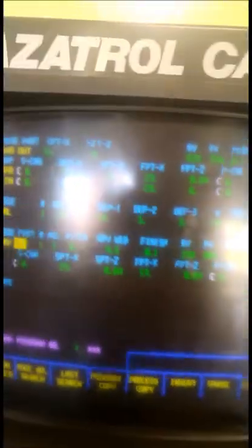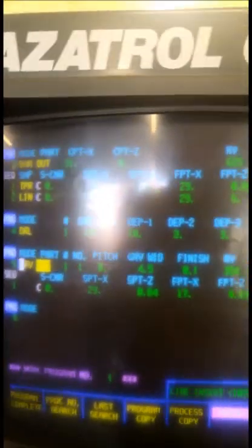I'll just leave that at what it is, because it's all going to be done in basically one cut anyway. Then you've got surface speed and feeds, which again, it's all just auto, but you can change that if you need to. Tool number 2. No real need for an offset in this one. Go down and insert again because I need another line there. Starting point in Z is 0, finish point in Z is 1, because I'm just doing a spotting off. And then I'll insert another line.